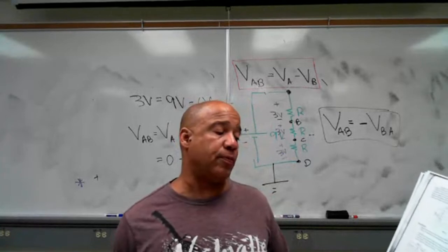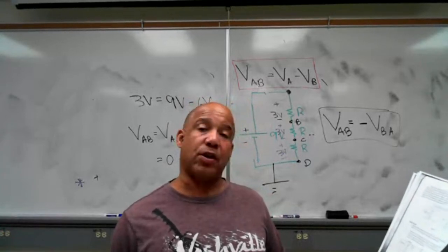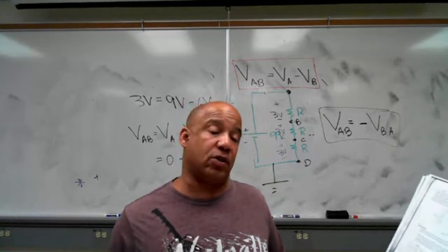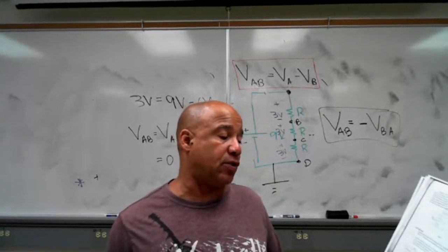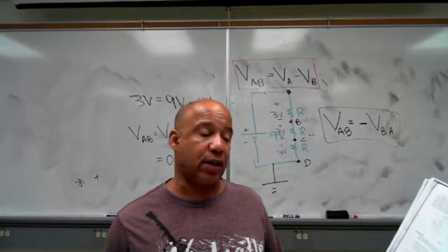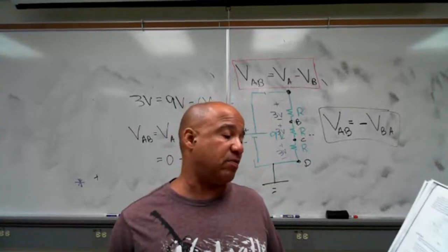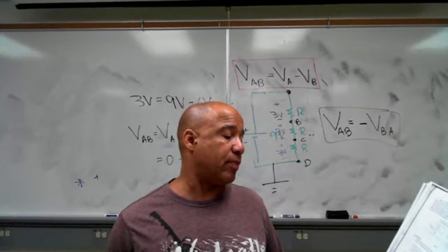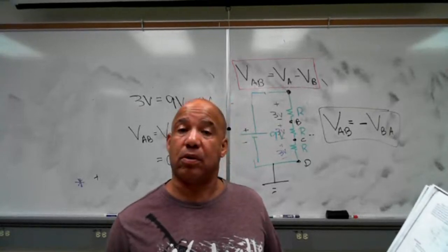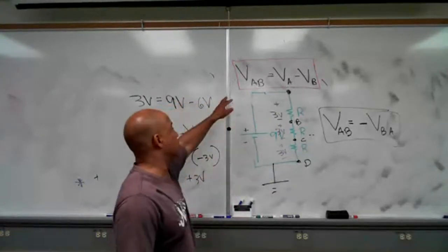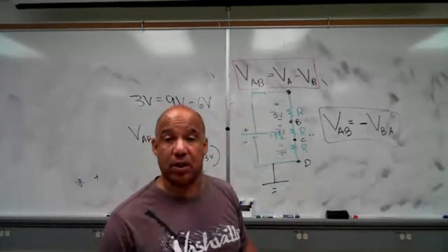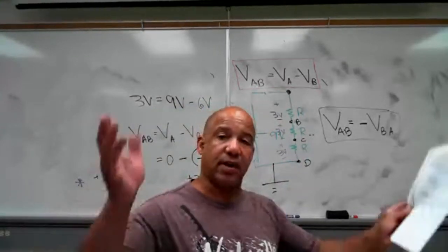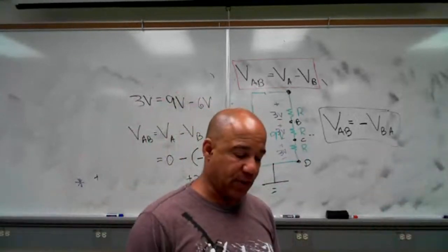So you'll use figure 4.2 to get the voltage drop across each resistor, and that's what you'll put in table 4-2. You just measure the voltage drops. But instead of giving you V1, V2, they're giving you those points. They're calling VAB just the voltage across R1, V1. And VBC in table 4.2 is just the voltage across R2. So they're using this symbol because they want you to use the double subscript notation and the single subscript notation. So you'll do that in table 4.2. That should be pretty easy. Build the circuit, measure the voltage drop across each resistor.